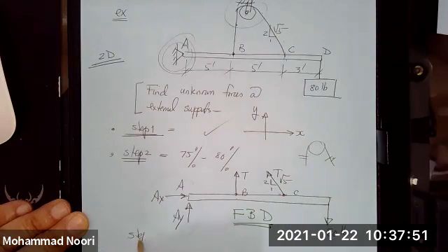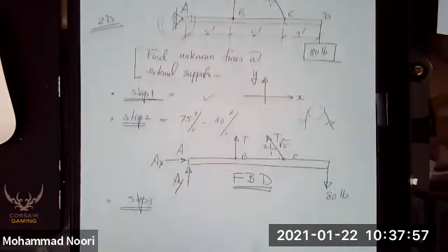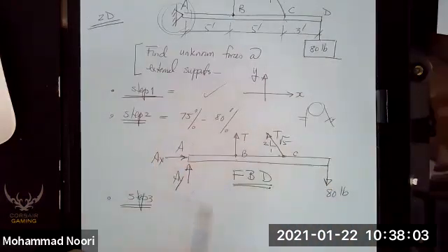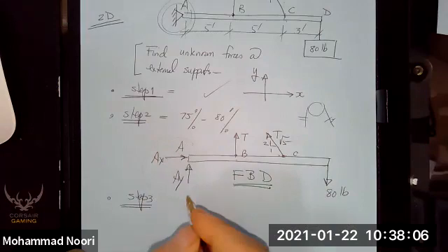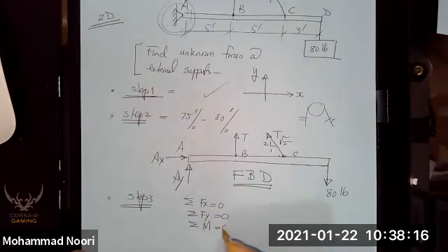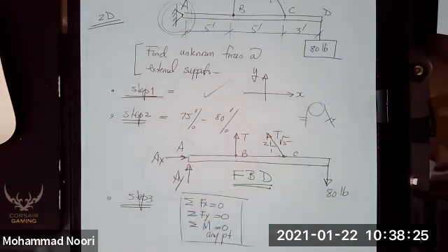Step 3 is the easiest step. Now you apply your knowledge of statics, which is knowing that this object subjected to these forces is in equilibrium. Your knowledge tells you sum of all forces along X, sum of all forces along Y, and sum of the moments that all of these forces generate about any point has to be 0. We call these equations of equilibrium, and in the case of dealing with 2D objects, we have 3 of them. That means we cannot have more than 3 unknowns.